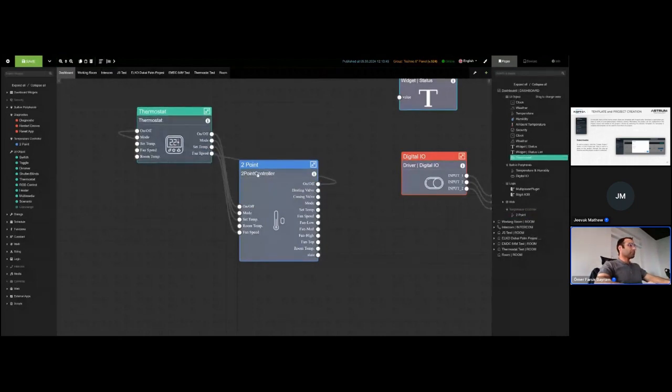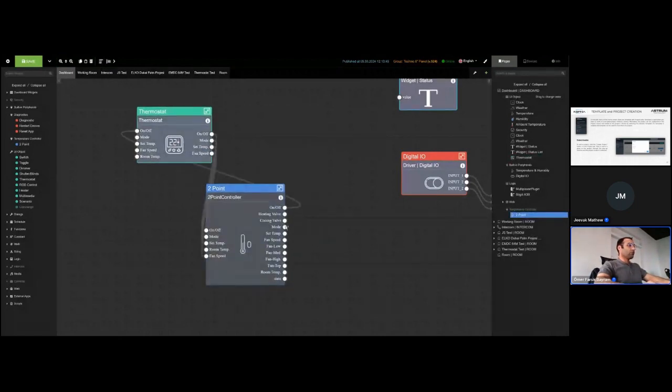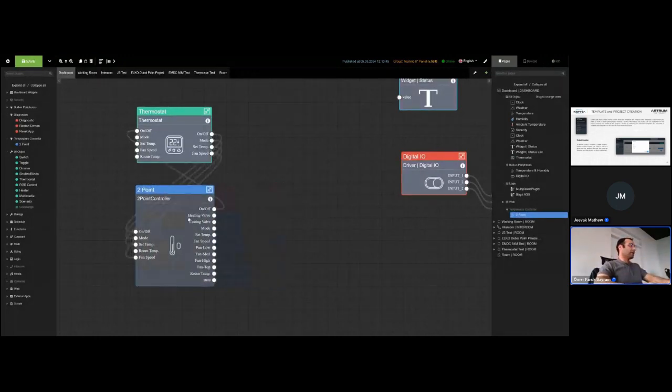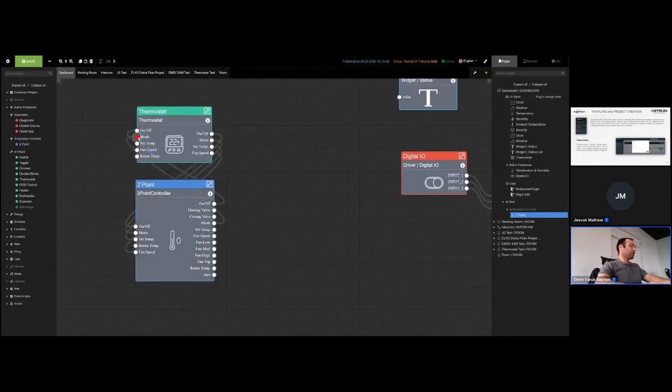Okay. Here, heating, cooling valve, we need a relay module. For example, INAS bus module, we can add as sample. First, let's connect UI and the controller connections. Set temperature, fan speed, room temperature as well.